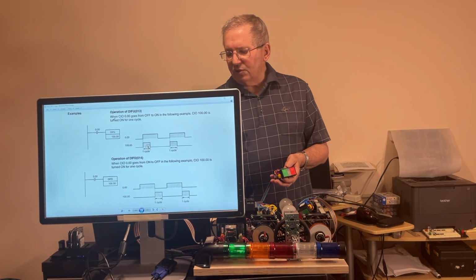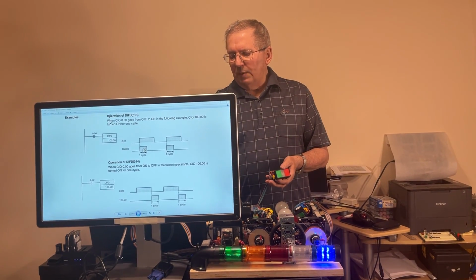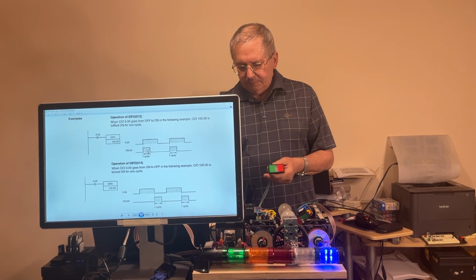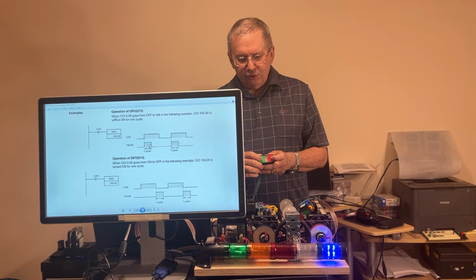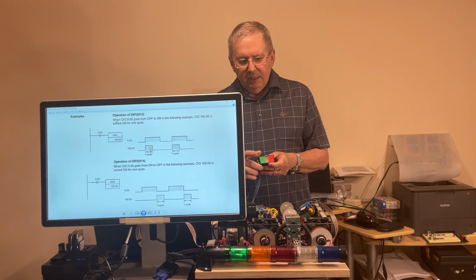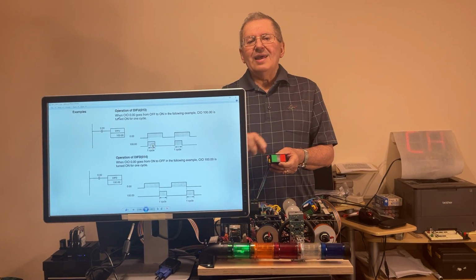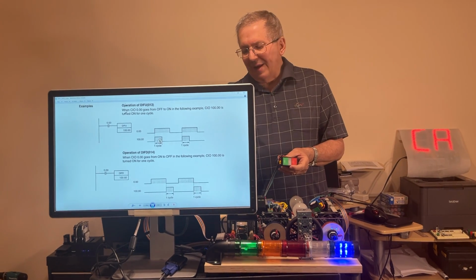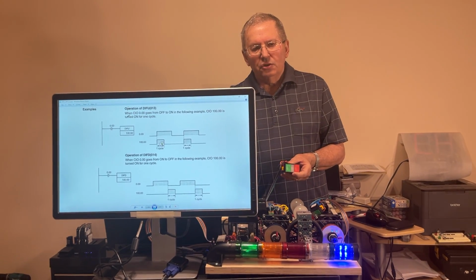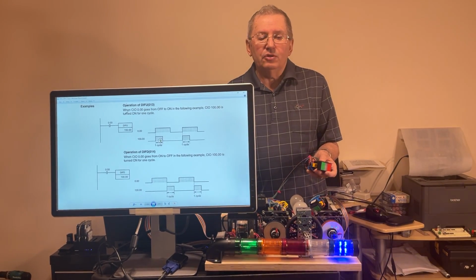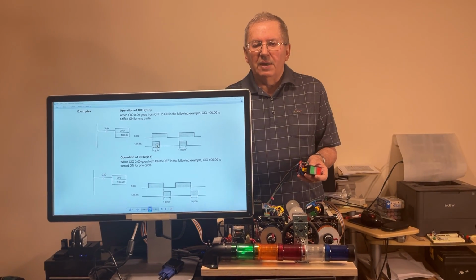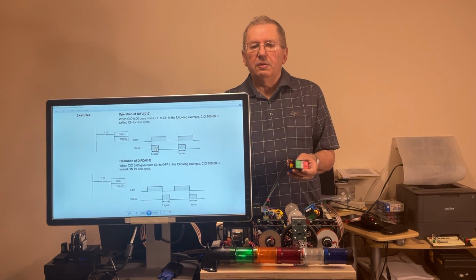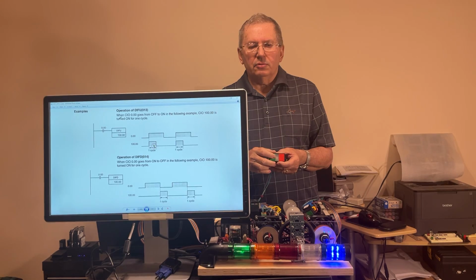The duration of such a cycle is from the moment I push the button until the next time the executing cycle is going to find that instruction again. So it's only the duration of one cycle, which is very short, milliseconds. But it's currently used to debounce all kinds of sensors.